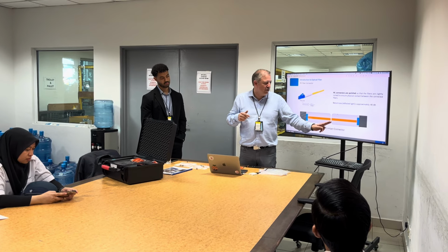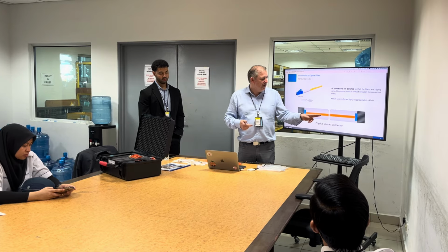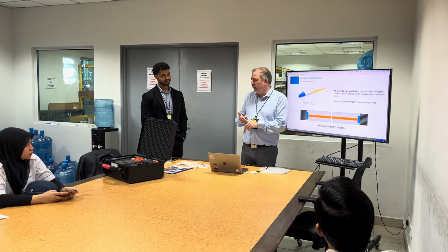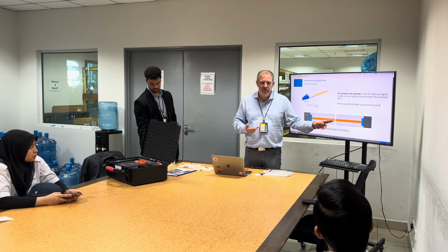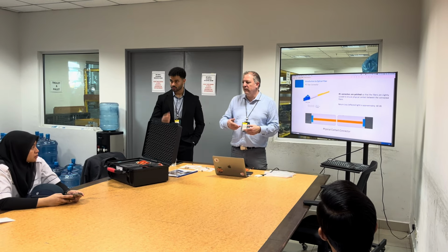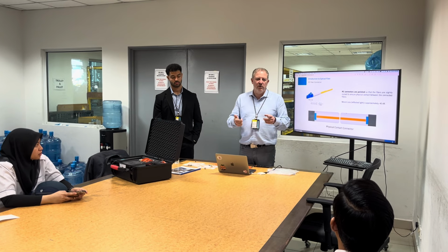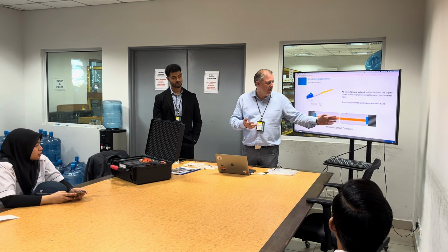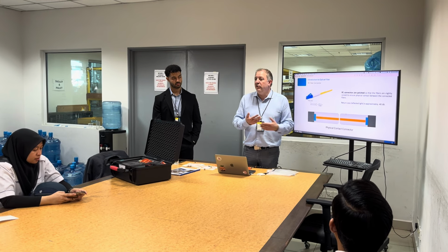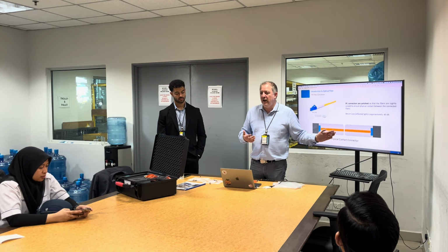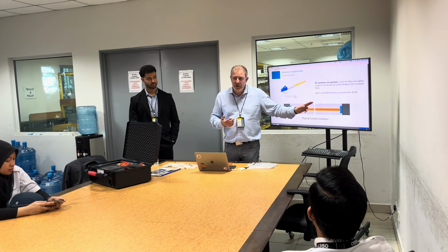Obviously, if you don't have physical contact, you will lose some of the power. If you have misalignment, you will lose some power. And if you have something in between, like, I don't know, water should be okay, but skydrol, dust, or any other small particles, then you may also lose some of the light. Also, if you damage the connector, it's perfectly polished here.